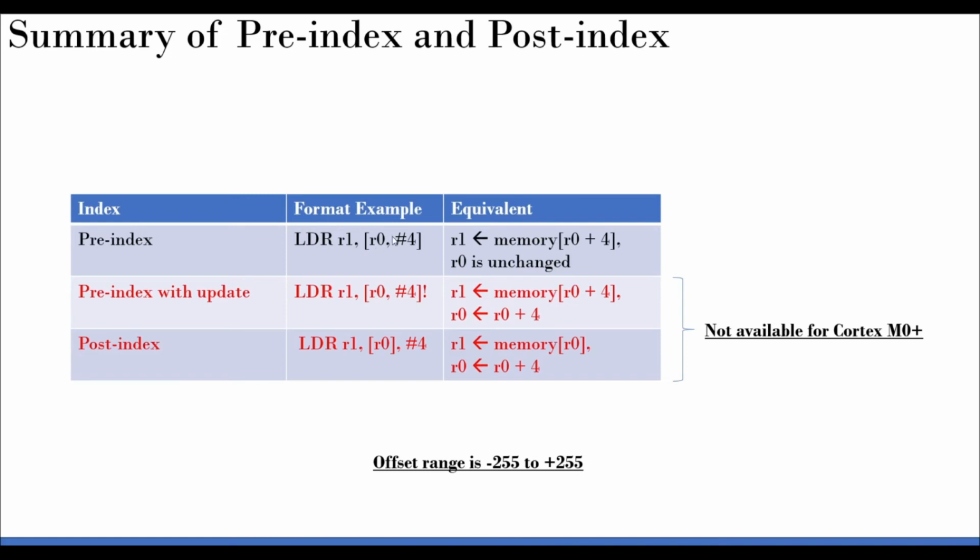The reason is, if you see here, this entire instruction is 32 bits, so LDR will occupy something like this, and what it essentially says is that this particular offset can take a limited number of bits. Not 8 bits actually: 2 raised to 7 is 128, 2 raised to 8, 2 raised to 9, right? So 9 bits you can take. That's why it's minus 255 to plus 255. That's the offset you can give.